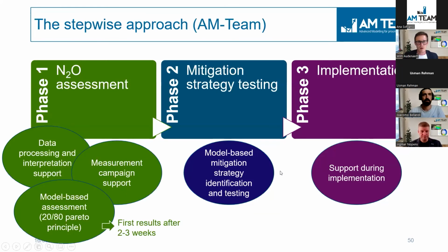So what we typically do is we work in steps, and one of the core purposes of this webinar was also to show that this tool is a practical engineering tool. Many people from past experiences, like 10 years ago, think CFD is not really a practical engineering tool. The thing is, nowadays computers are very strong. We have applied this model, I think, at around 100 plants. This CFD biokinetic model, it's really a routine exercise, and you can have first valuable results after 2 or 3 weeks in such a project, and it includes intermediate meetings and things like that.